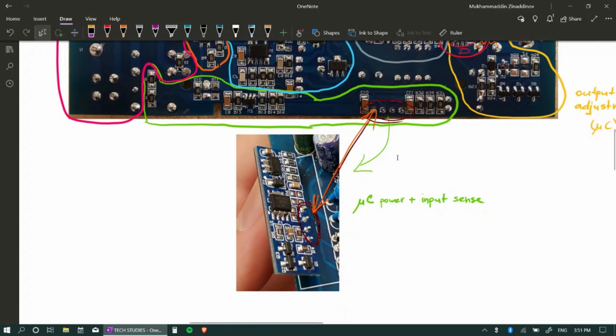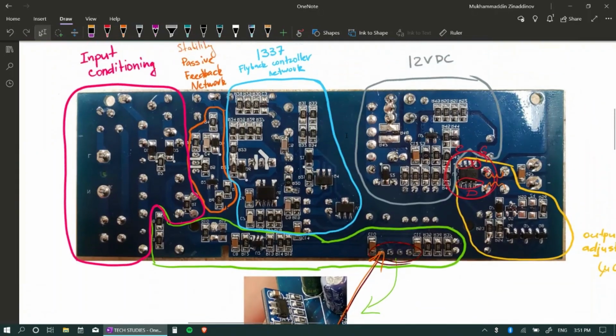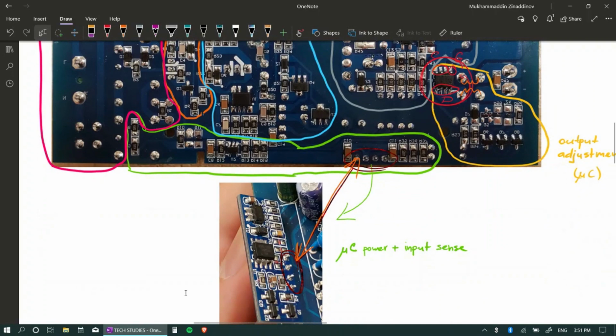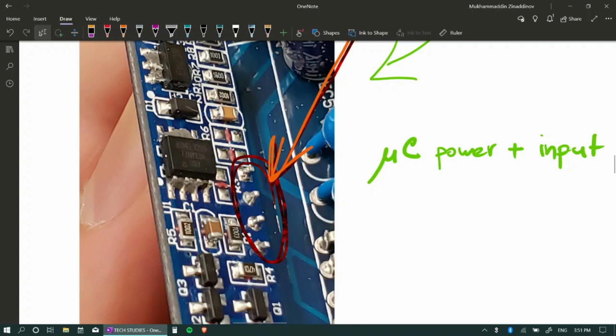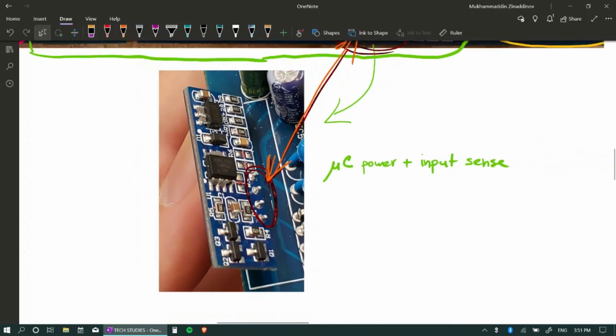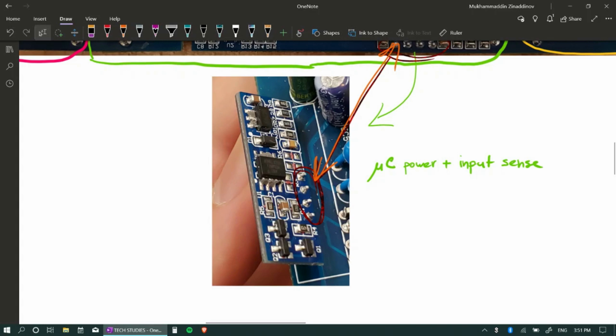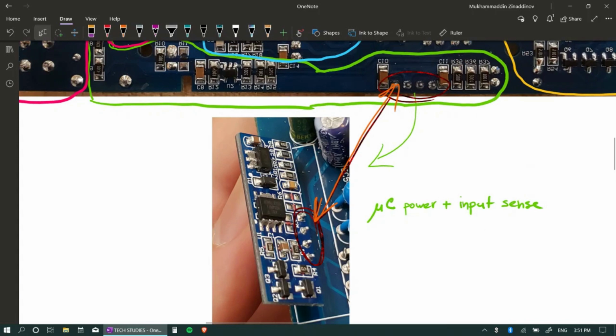Here we figured out our active controls. In this case, by the way, the microcontroller that is used is the ATtiny13A. So it's the AVR family. This board, by the way, I tried to shine light through it and it does not propagate through, whereas in this case I can clearly see the paths on both sides when I shine a flashlight through the board, which means that this is not a simple 2-layer board. It probably has 3 or 4 layers.